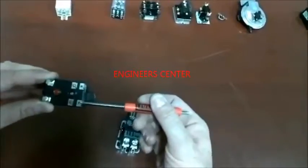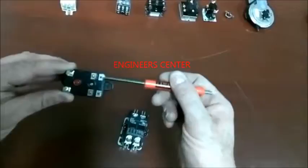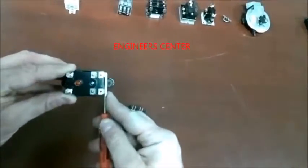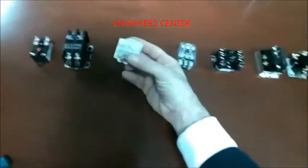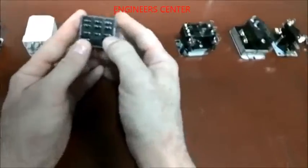and you had power here, it's normally open, and so this terminal and this terminal are normally open, meaning they're not connected with continuity. But if you give this 24 volts, they become closed, and so they connect, sending power through the other side, just like this. And so this is also a relay, just the same thing. It just looks a little different. They like to confuse you, but originally this is just another relay.